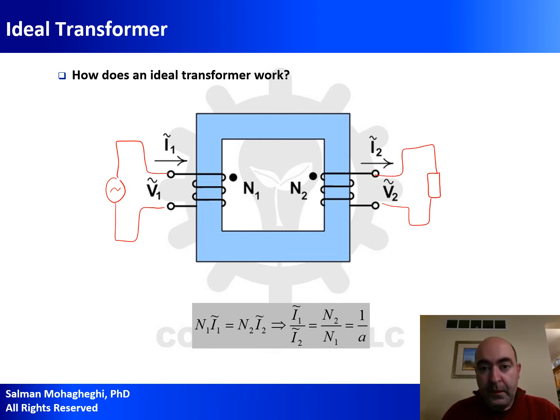Now, from magnetic circuits, you probably remember that every time you have a winding wrapped around a magnetic core which has a current flowing through it, we model this as a magnetomotive force. Magnetomotive force essentially is the effective current that is being applied to that core. The current that generates that magnetic flux, and the magnetic flux starts flowing through the magnetic circuit.